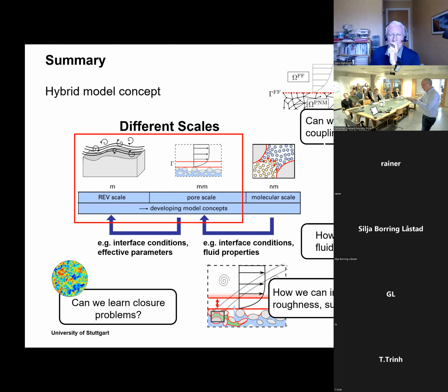The second one is, on the other hand, if there's only one eddy, then in the front of the flow field you have a tiny viscous sublayer. And related to this tiny viscous sublayer, you have a high velocity there. You get a high diffusive part related to this gradient. And behind this, on the other side of this peak, you get the opposite. Why? Related to the decrease, you get a relatively thick sublayer. You then get an advective control system and not a diffusive control system.